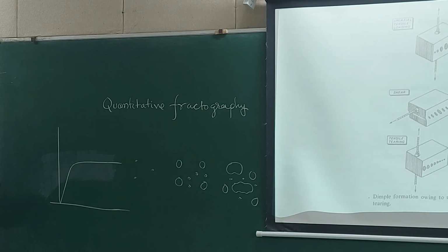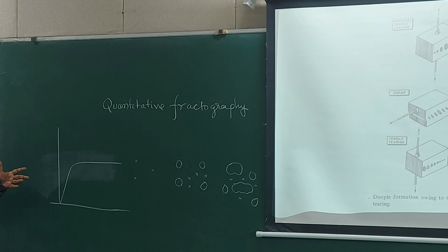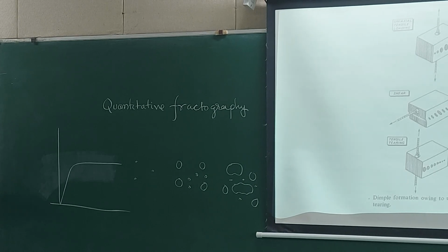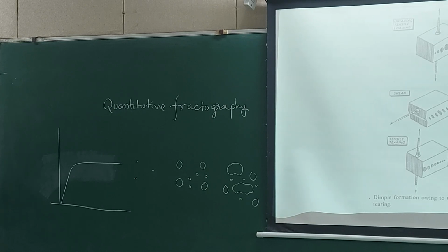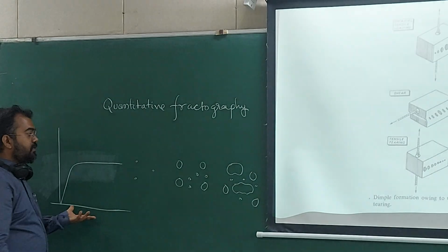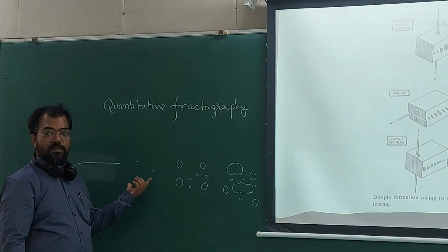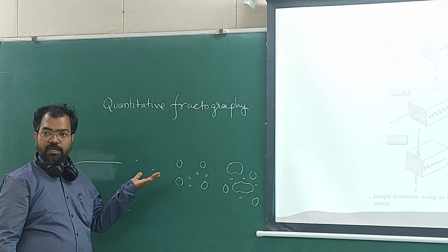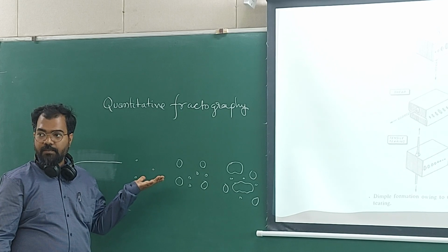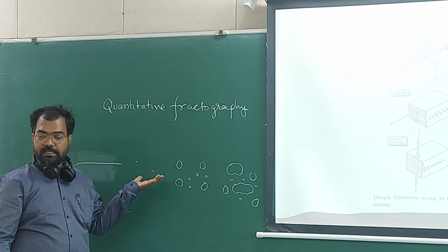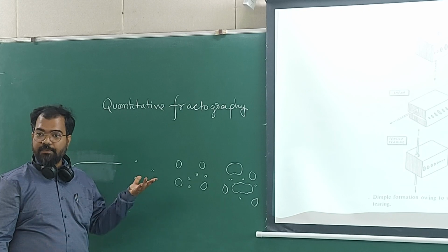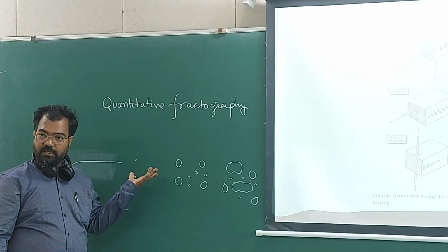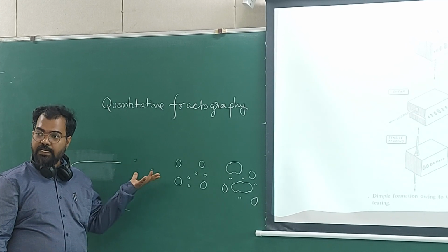Okay, so it has a lot of slip systems and stacking fault energy is good enough so that cross slip can happen. And so dislocations are not feeling much barrier, so strain is accommodated by the deformation. So in that case, when damage initiates, you will have the nucleation at whatever grain boundary. So nucleation sites are not manifested by the material's deformation capability, but by the grain size and things like that.